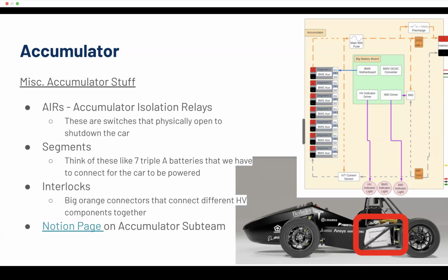that's inside the inverter. Because, right, if you disconnected these systems and the capacitor in the inverter was just open, now your system is still energized, right? You still have that capacitor there. And if you know about how capacitors are different than voltage sources, that can actually, if you touch it, release a lot more current a lot more quickly. So that's actually more dangerous at that voltage, depending on how much capacitance it has, how much energy is stored in it. Anyway, we can go into that more later. You have the discharge circuit.